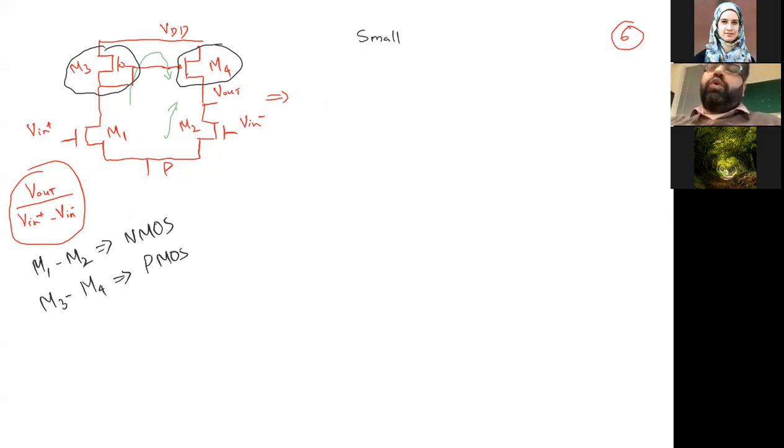So for the source of PMOS, it is all the time connected to VDD or the highest potential, and the source of NMOS is connected to ground. So there is no separation. The bubble sign also shows it's a PMOS, and without the bubble is NMOS. So all of these things are the same.